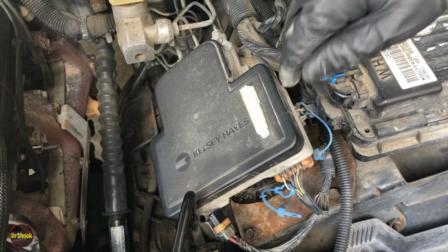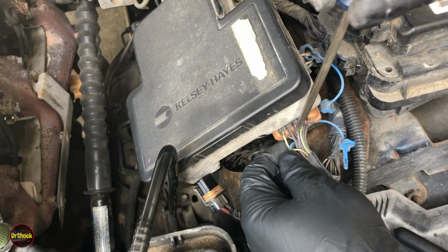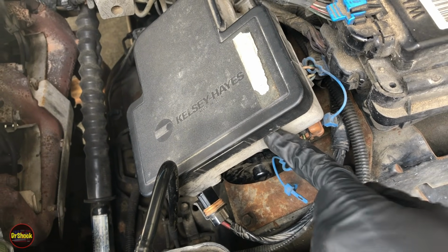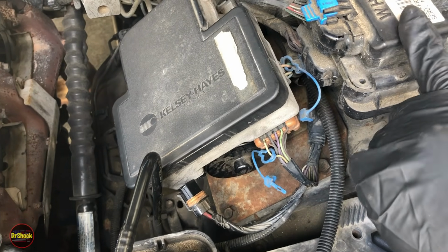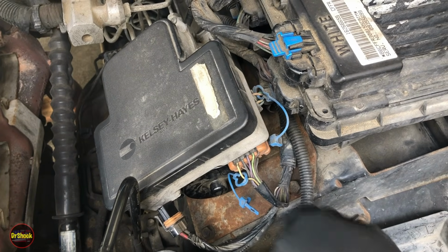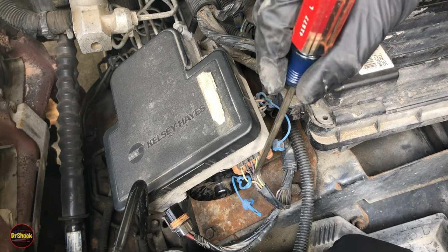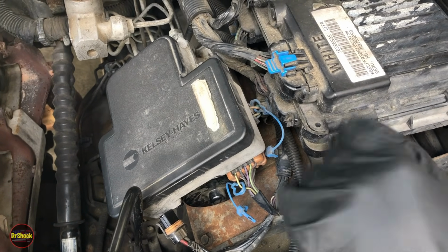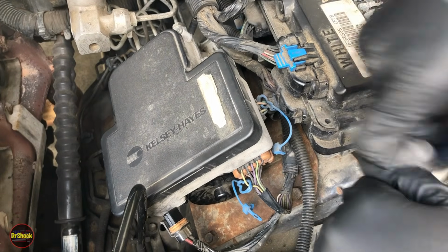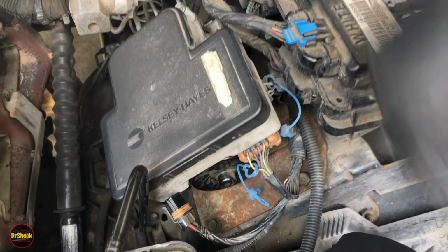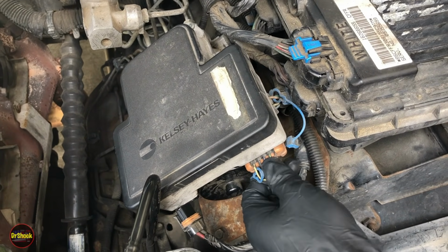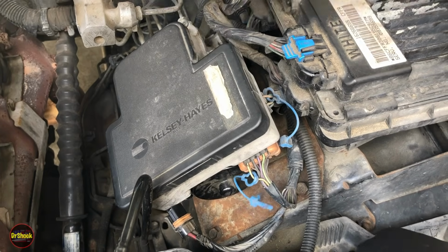One of these wires here, I think it's this guy here, the purple one, is actually the serial data line between the EBCM and the pass lock module and the VCM, or the PCM if you have diesel. And if you damage that line, the engine won't start. I've seen that on trucks before. This line gets shorted or damaged, and if the VCM can't communicate with the pass lock module, it goes into theft mode. You'll get the security light and it won't fire up. That can happen because it has to go through here in order to get to there. So we definitely don't want to put too much stress on this connector. So we'll come and get that later.